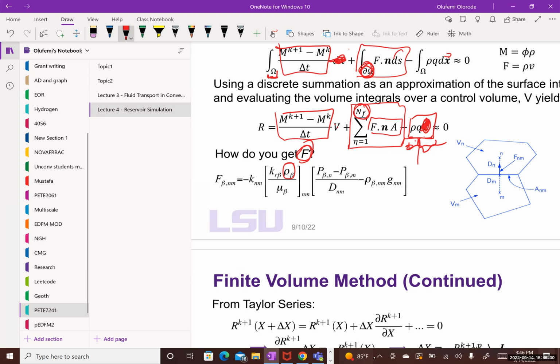Some people have tried to write a simulator based on the pressure squared approach. But if you remember pressure squared approach, that was, is it Aluseni? No, Aluseni is the pseudo pressure stuff. But those are all based on analytical stuff, well testing, analytical solutions. So you're trying to simplify it so that you can solve it with a simplistic solver. But when your equation is non-linear, just implement it as is. You're going to use a fully implicit method.